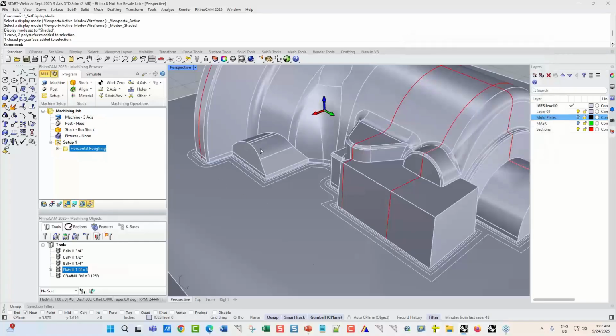Okay. Well, it's done, but one of the things you can do to speed up, if you're doing what-if scenarios when you're machining, I would recommend setting slack tolerances and generating it. Things will go quicker. And then once you've got the program all figured out and exactly how you want it to do, you can come back in with your final tolerances and do the final programming.